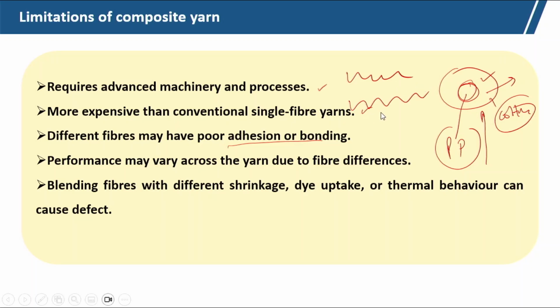If the core is shrinking to a higher extent than the sheath, then the core will give an inward pulling force to the sheath and it will form a wrinkle-type defect. So, that is there.